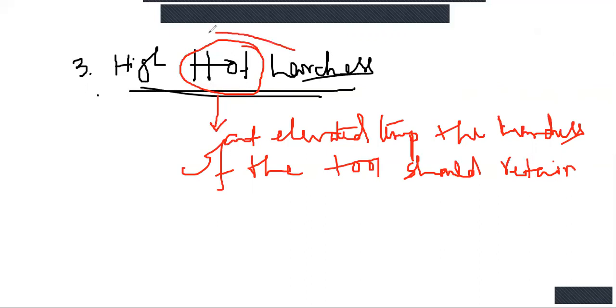Because there is a situation when the tool and job are continuously in contact. There is frictional energy released by the job or tool, so that a high amount of energy is released, and the temperature at the contacting zone between the tool chip interface is very high.